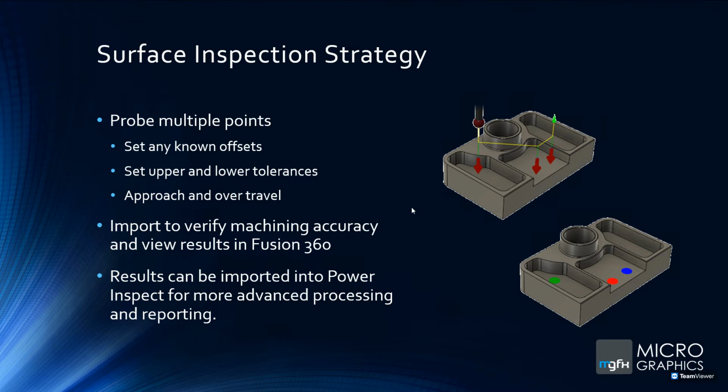And if it runs out of over travel, let's say 10 millimeters, and it doesn't touch the part, it will return an error into the log for that position. It will say that measurement was not taken.